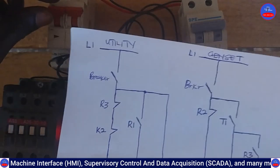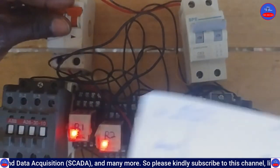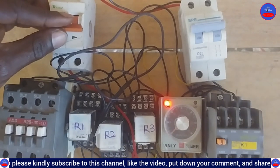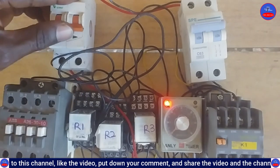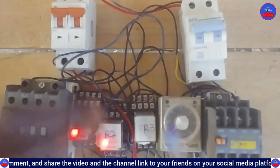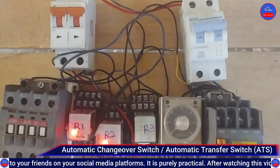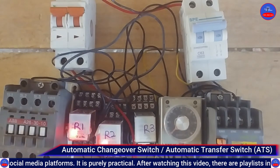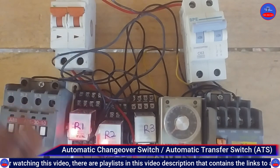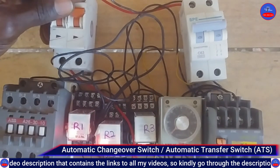So let's assume that the utility power goes off again. Let's see what happens. You see, it's off. The generator output is not on, and then for some time it will come on again. Though the engine will still be running, because there was a delay time, the time the utility went off, the output of the generator didn't switch on at that same time. It delayed for some time, waiting to ensure that the utility doesn't come on again. Let me demonstrate for you. Off. It is delaying. On.